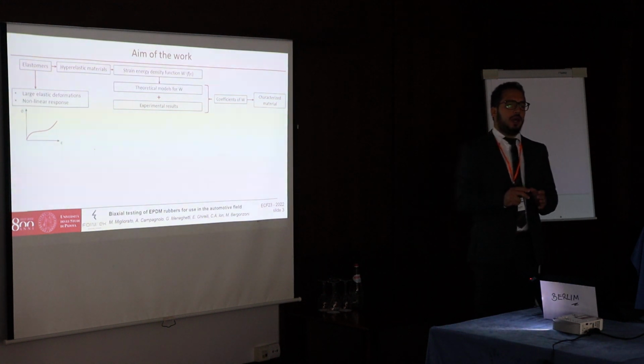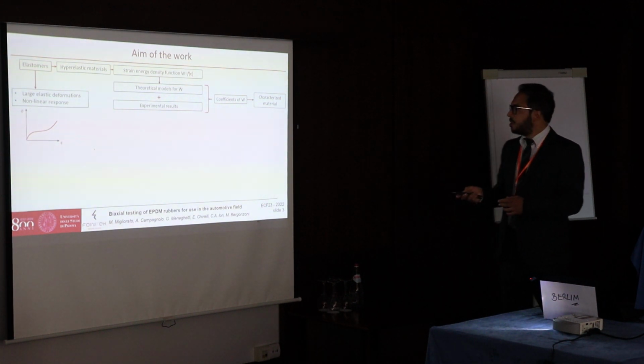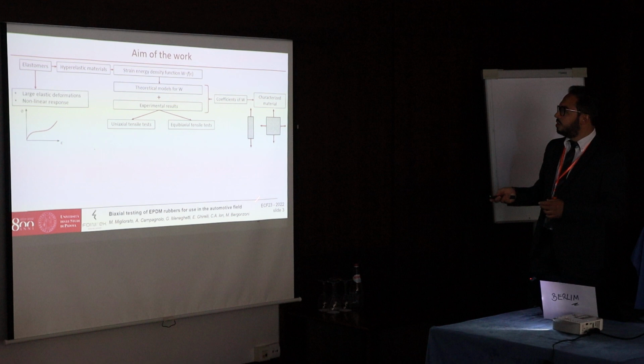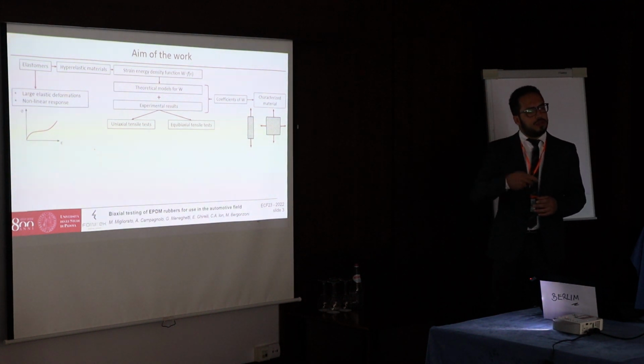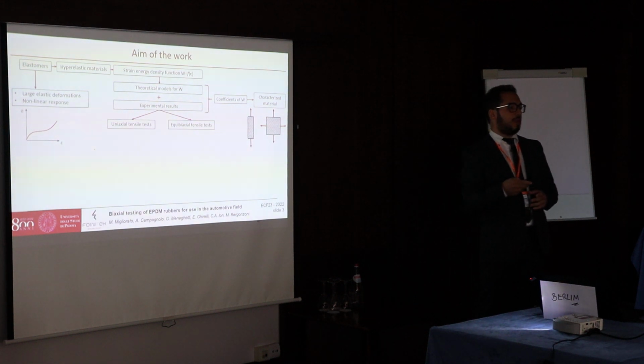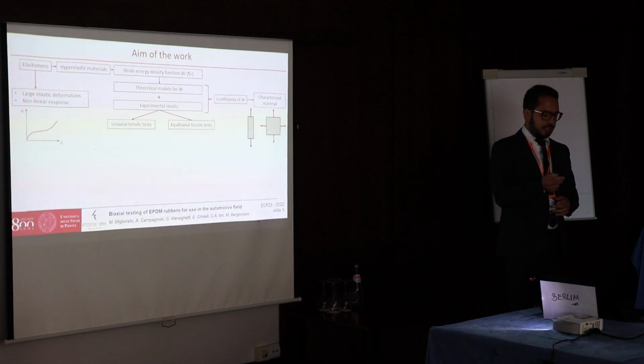However, to properly characterize the behavior of elastomers under a generic stress state, a uniaxial tensile test is not sufficient, while experimental tests under different and complex loading conditions must be performed, typically combining a uniaxial tensile test with an equibiaxial tensile test.